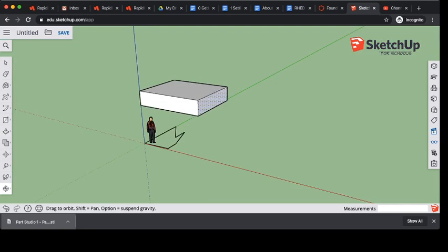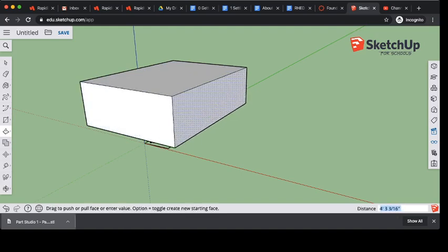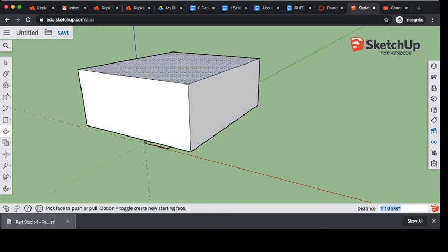And so what's really nice about SketchUp, what it does really well compared with tools like Onshape that are more geared towards precise things, is you can just click and drag circles and make things however big you want them to be. It makes it really easy to freehand your designs. For example, if I drew a sketch of something here on this surface, you'll see that it's now shaded in. I can use my push-pull tool to push that out and make it 3D.